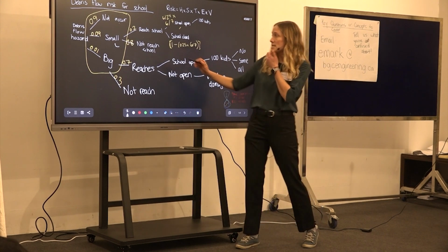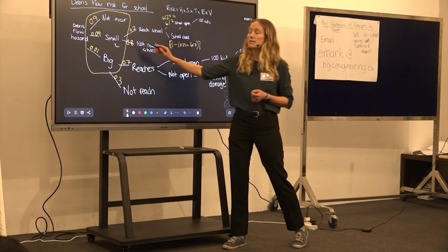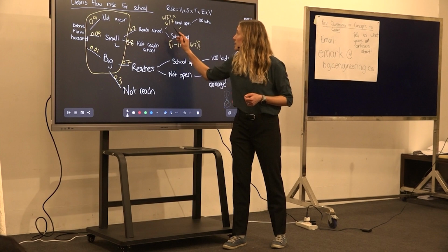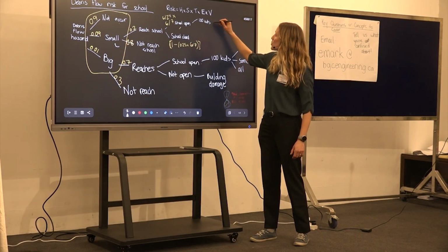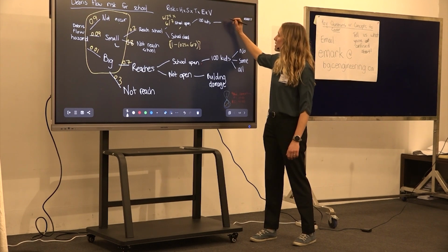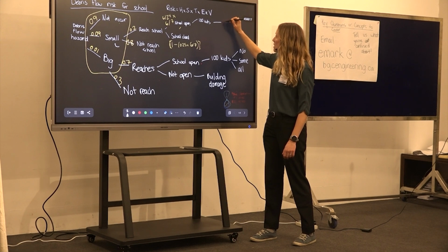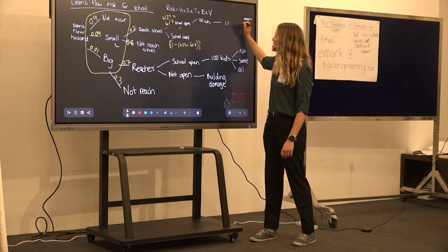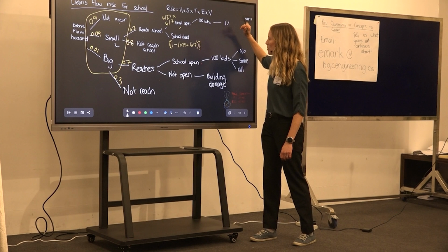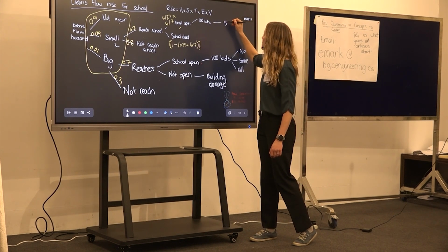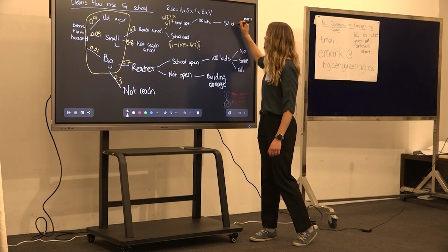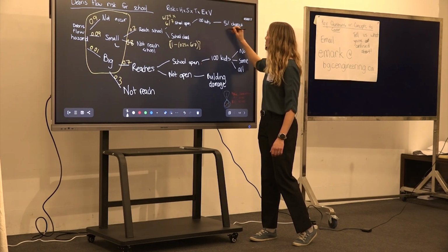And so we're going to say that for this small debris flow, if it reaches the school, then for each person, it's probably pretty small. So let's just say it's like 1%. Let's make it more interesting. We'll make it 5. There we go. 5% chance of fatality.